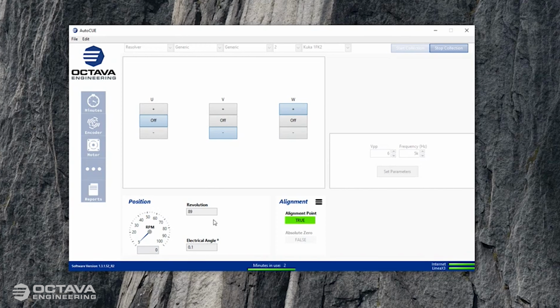You can see that because with the rotor locked in that sequence, I'm crossing over that 0-degree electrical angle and it's resting at or pretty close to 0. So you never want to remove a feedback device until you know what that lock-in is. Most of the time, it's going to be predefined in our software already if it's a feedback type we support. But in this case, when you're creating a new one on your own, always want to make sure you know what that alignment is before you remove the resolver.